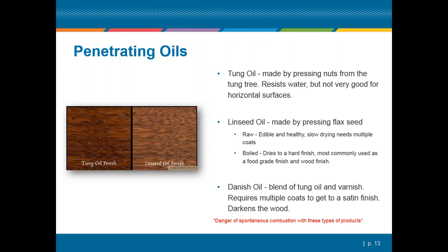These don't re-wet the same way that shellac does. Whenever you put another coat of shellac on top of each other, it re-wets. With these particular products, once they're dry, whenever you put another coat on top of it, then you're building another finish coat over the top of it. But yes, they can be recoated if necessary, or if some scratching occurs and so on. They can be recoated with themselves the same way that most of these finishes can be.